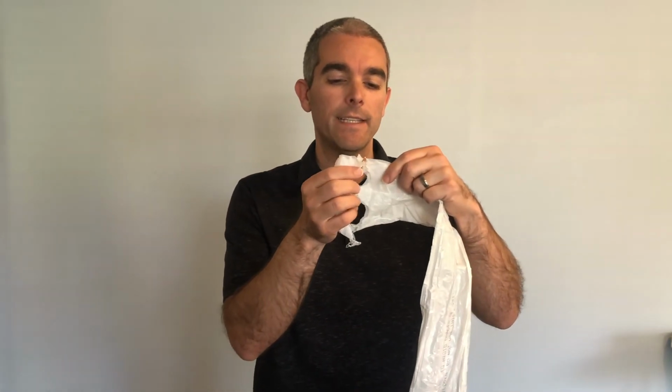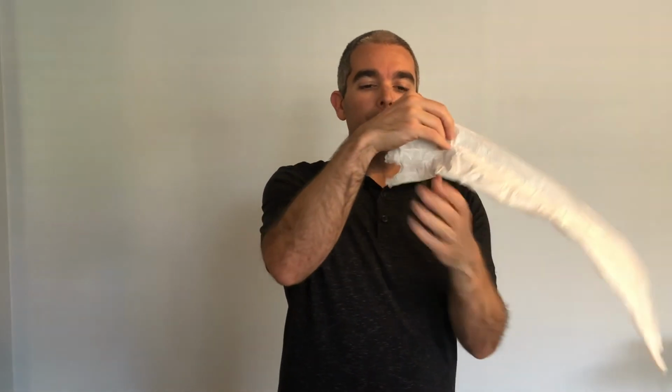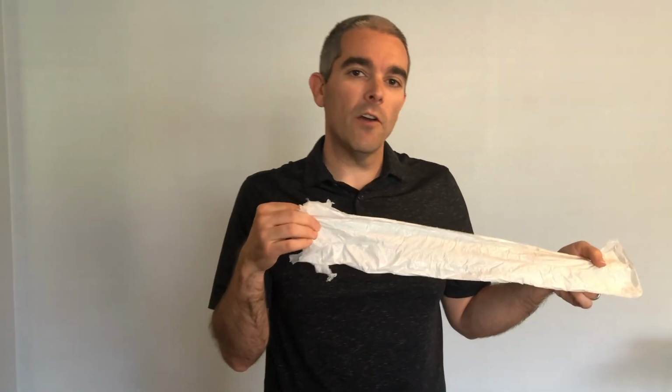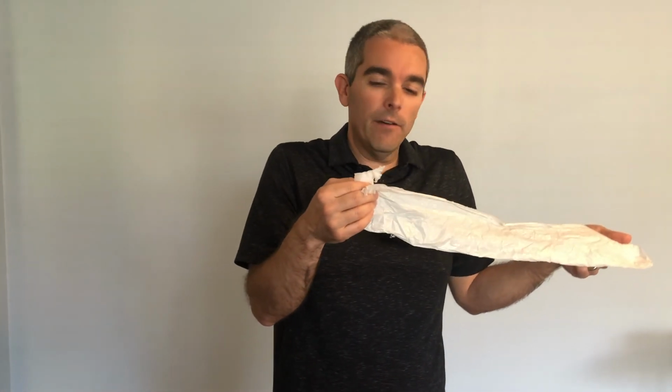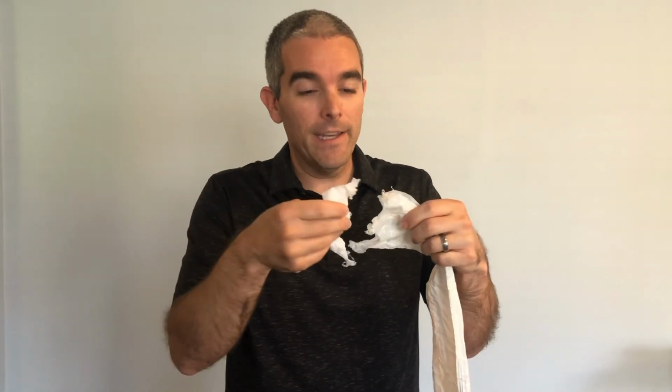However, when we look at it just in terms of the overall length of the member, when I experienced yielding at the connection, I only stretched a very small amount. So we have a very limited amount of stretch right at the connection, and we're not really concerned about that. If our connection stretches just a little bit, the member is still largely useful and we're okay. The only problem we run into is if the connection stretches and then it eventually reaches its ultimate capacity and then the connection fractures and separates. That's when we have the big problem.